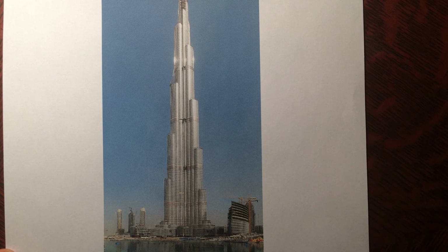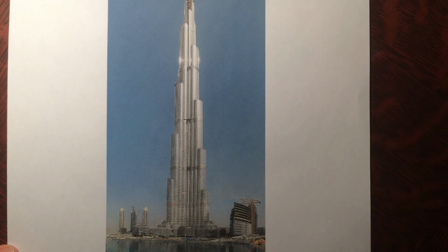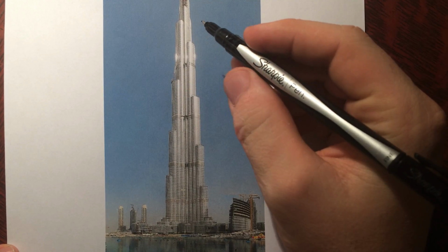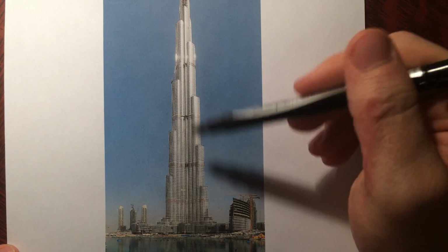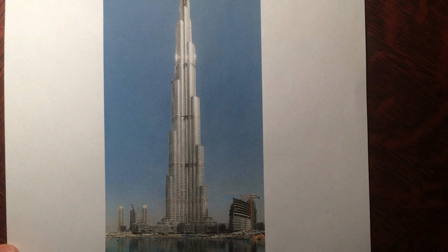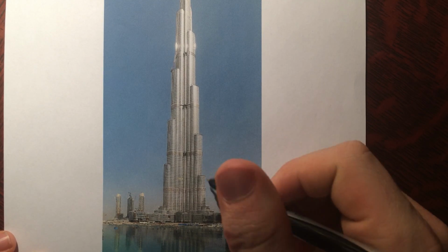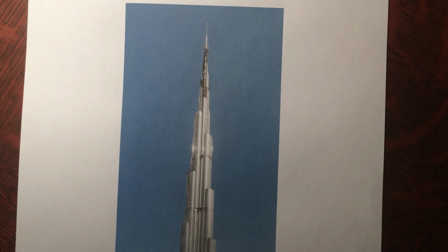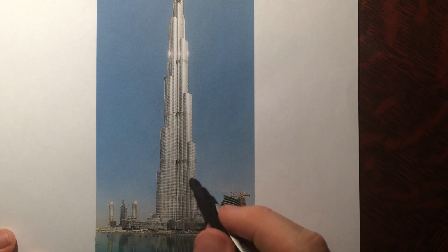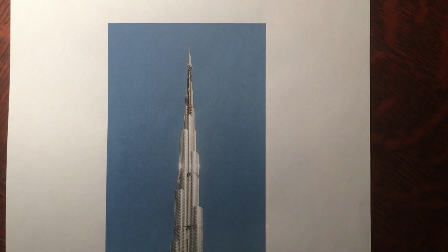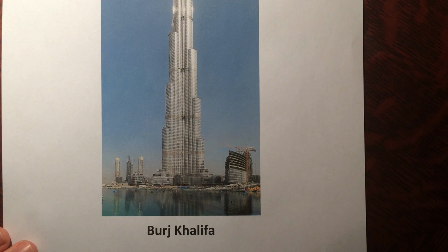It's got 330,000 cubic meters of concrete. I mean, that's just a lot. And in that concrete, there's about 61,000 tons of steel. So all of that is being compressed or in tension, wherever you are in the building. And there's a temperature decrease from the bottom to the top of about 6 degrees Celsius. So you can imagine it's really hot down here, so the metal's expanding, and up here it's relatively cooler, so it's shrinking up there. So you've got to take all these things into consideration.